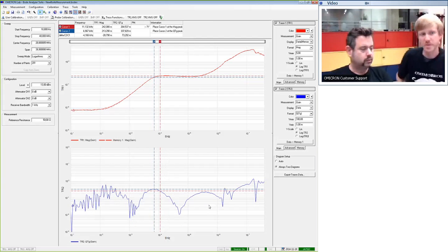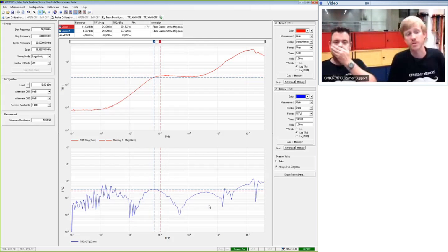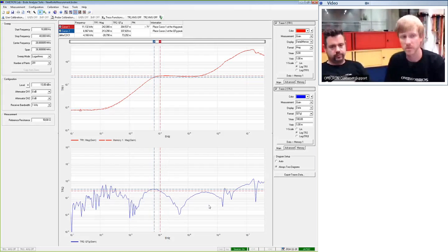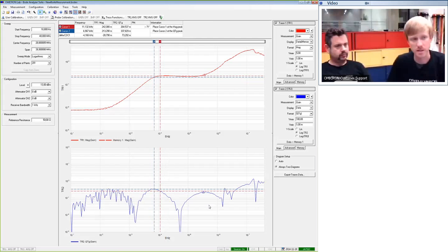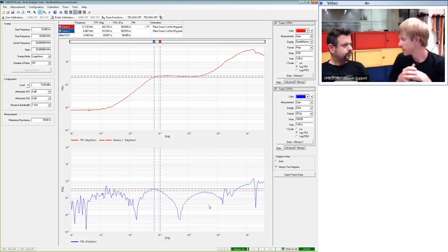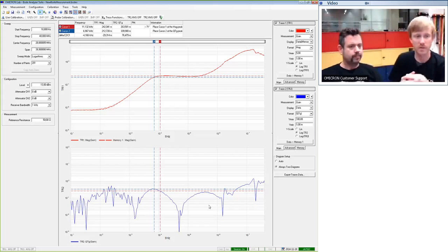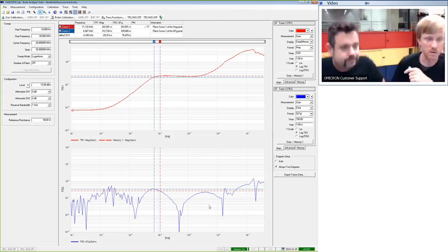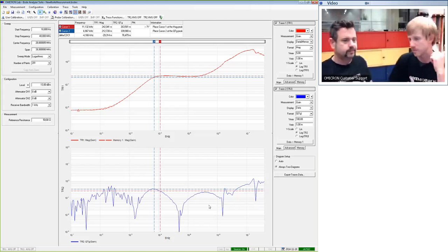Well, sometimes people ask us, why do you only show the result up to 71 degrees? Why don't you measure more? The reason is that we cannot measure higher than 71 degrees since the system is already damped so much that no oscillation will occur, and we cannot measure a peaking. So if there is no peaking, if there is no oscillation, then we cannot really measure the phase margin with this method. But if I know that my system has more than 71 degrees of phase margin, then I'm already quite happy with that.